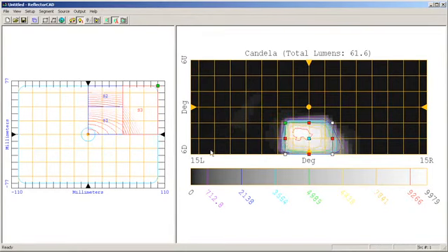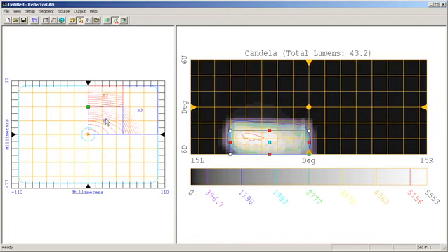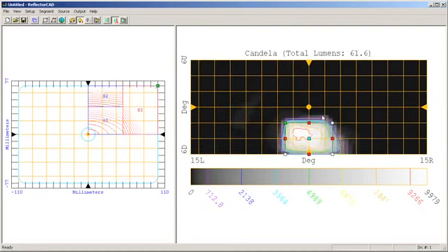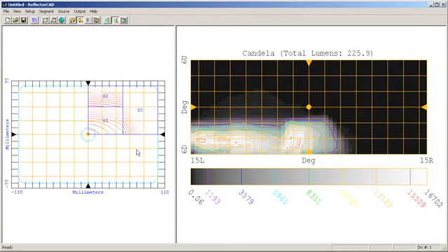You will note in the design that I'm doing, I'm actually tilting or adjusting the luminous intensity patterns from the inner segments to correspond to the luminous intensity pattern on the outer portion of the beam. And the segments which are furthest away from the lamp actually correspond to the luminous intensity patterns at the center of the beam itself. This is a standard practice in designing segmented reflector systems. What we can see now is the sum total of the distribution of those three segments.